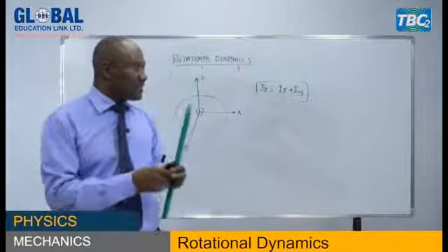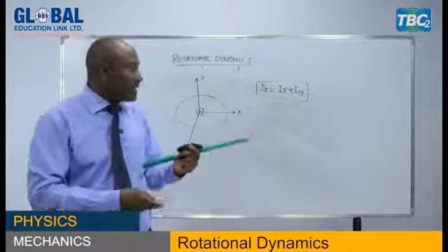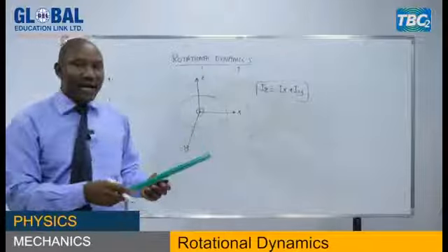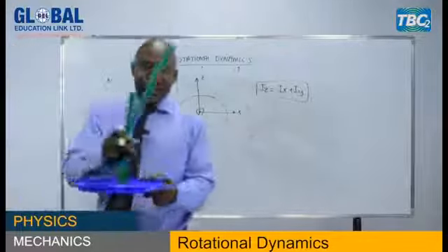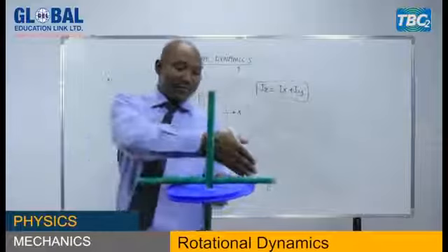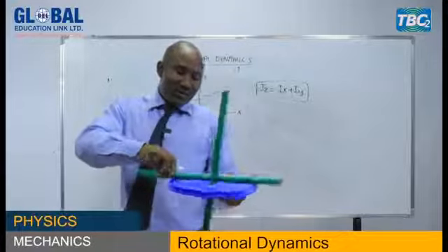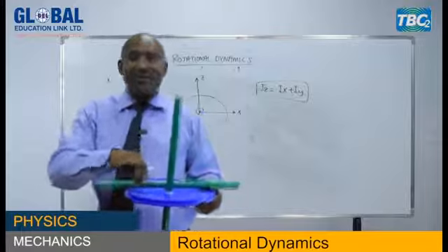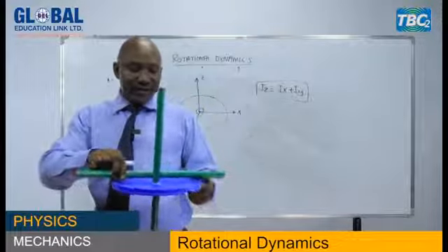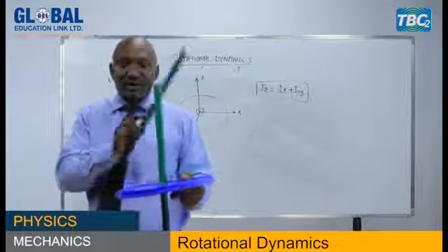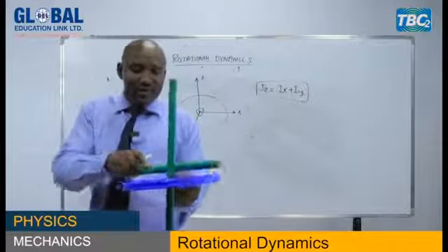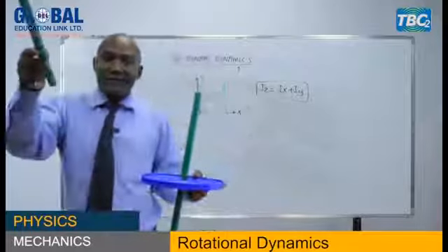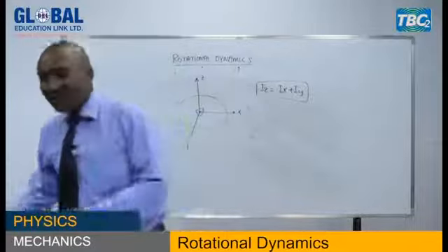Now, it's very difficult to see, but if you look at a disk like this, we know the moment of inertia about this diameter here. This is X, or this is Y. The diameter divides this plane into two halves. The moment of inertia about this is the same as the moment of inertia about any other, because whichever point you choose, it is a diameter. So the moment of inertia about any axis which is a diameter will be the same.